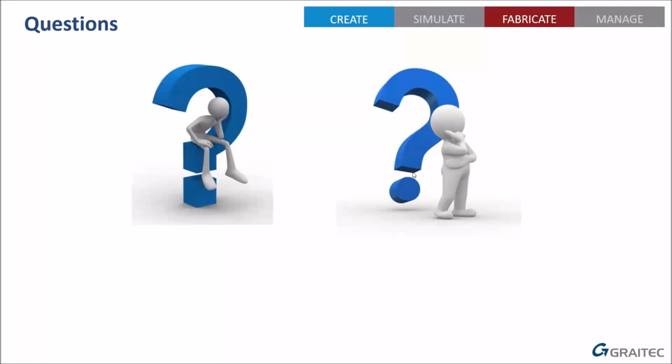And you can untick the X, Y or Z boxes so it only moves in the direction you want to move in and doesn't go up or down depending on the reference points you chose. You don't want it to suddenly move up by 20 mil, so you can untick one of the boxes to say no, I only want it to go in this way, and you're able to get the stair back in the right position. Something we actually do in our architectural metalwork training day, which is the day we use out of our standard course.